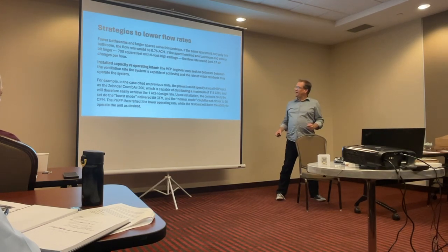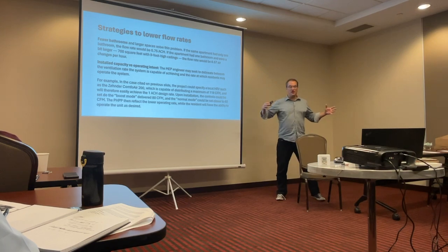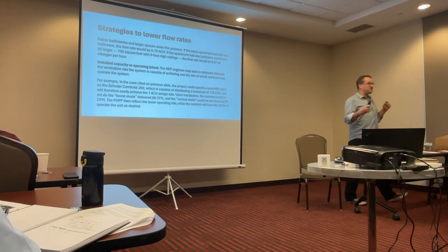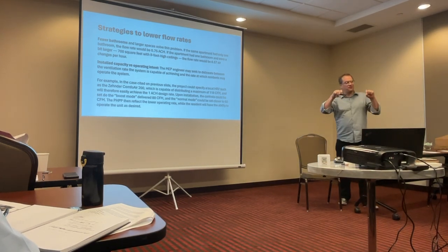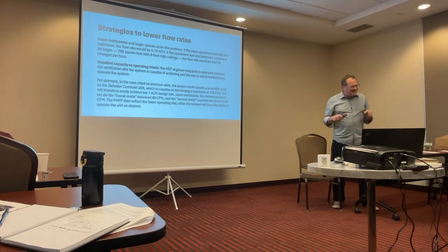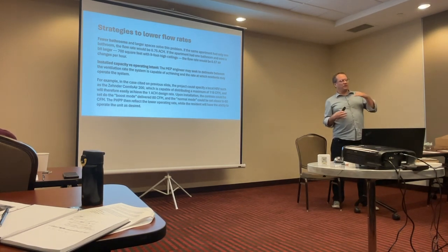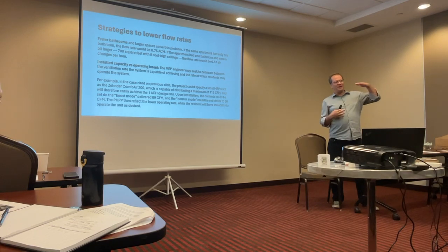Now, if you had one less bathroom, if you had 9-foot ceilings, if you had a little more floor space, if you weren't so cramped in some ways, that equalizes itself really quickly. So the number one solution, if doable, is not the mechanical fix, it's back to the architectural design. Do you really need 2 bathrooms in a 600 square foot apartment? Really? Is there really any extra privacy in a space that small? In a mid-rise, small 4 to 6 story building, could you make 9-foot, 9.5-foot ceilings? Then this math starts to change.